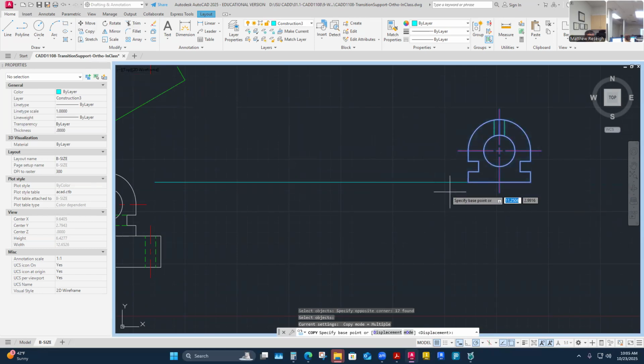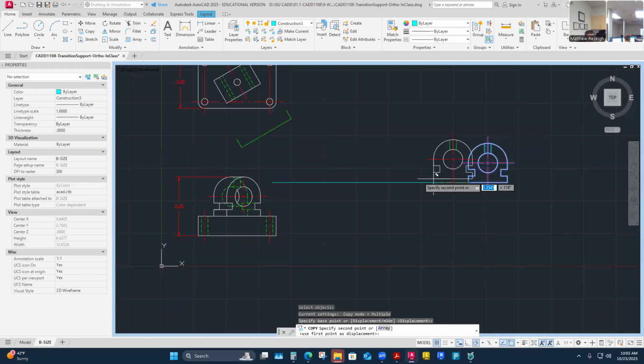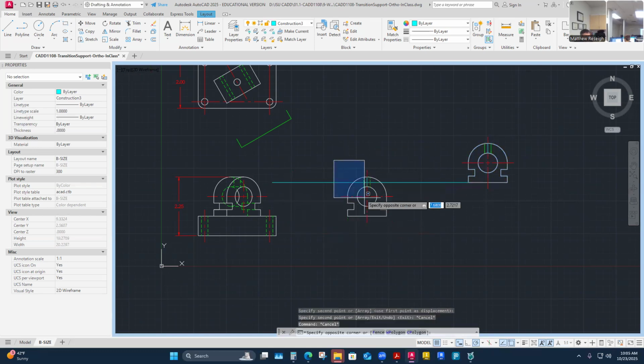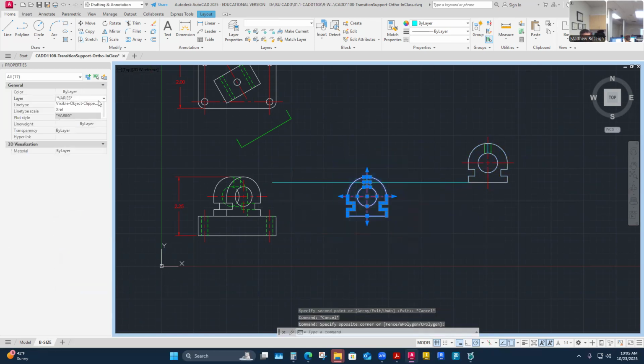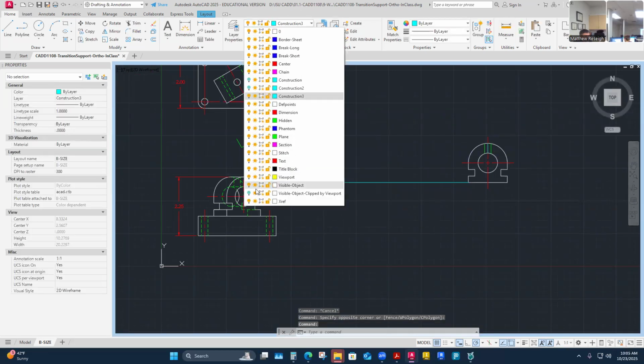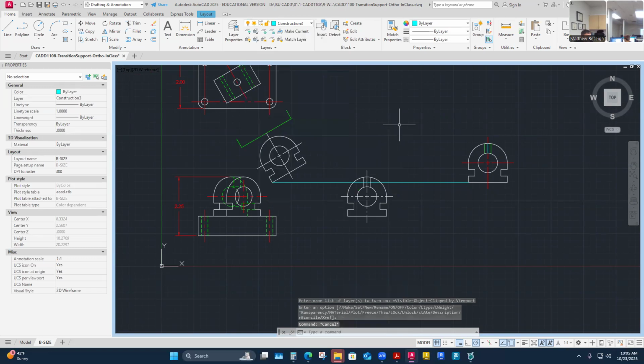So if I make that copy, this is in orthographic alignment with the actual view where I took it, but I want to reference this as almost this view here. So I want it to be in orthographic alignment here. And all I'm using it for, I'm going to push it to that same layer that's turned off right now. And I'm going to turn that layer on real quick. So I get both those ghosts.